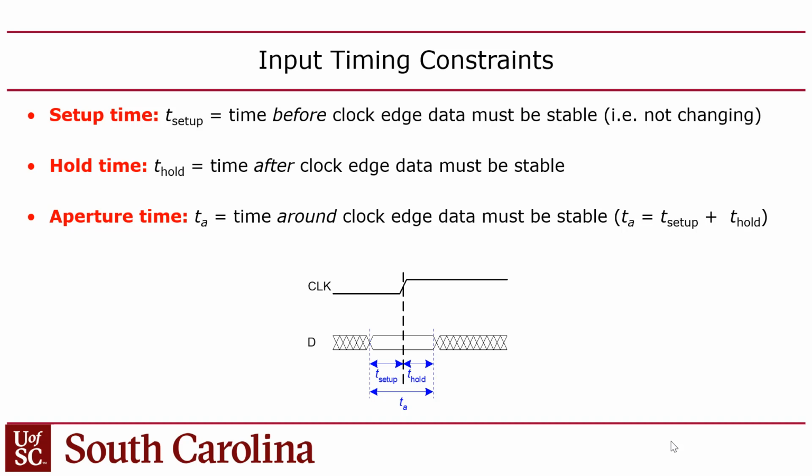When you think of a register, you think of it as edge sensitive. So when there's the clock edge, whatever the input is on that register is sampled during the clock edge, right? During a really small time as the clock is going from low to high, right?